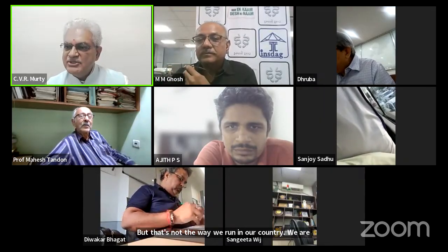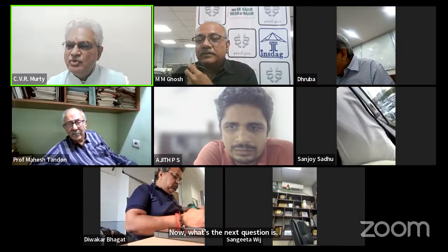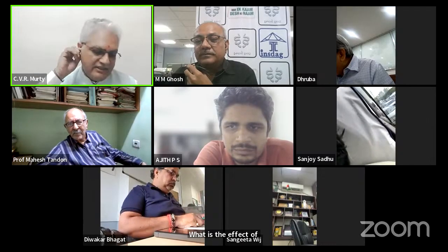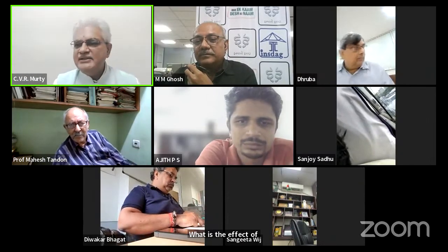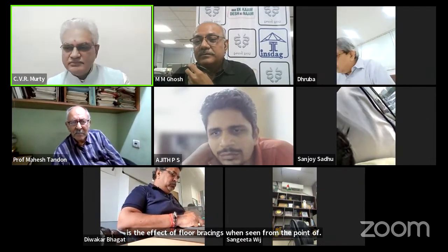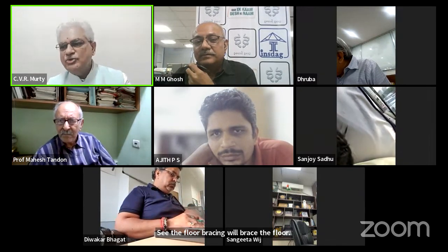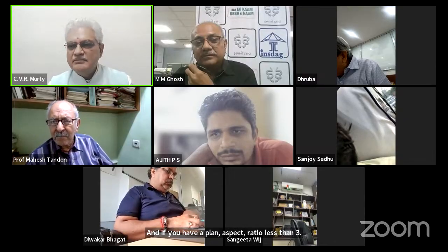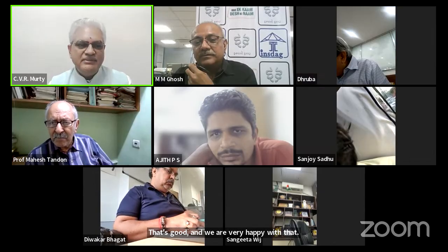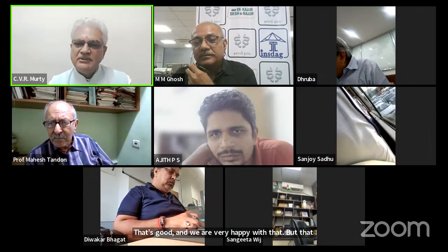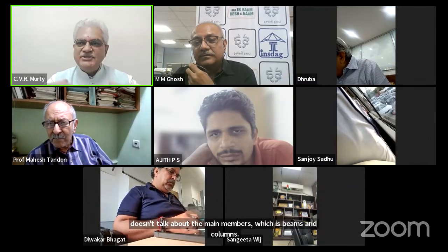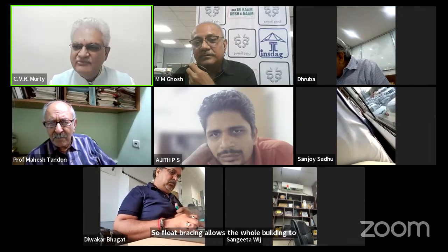Now, what's the next question? What is the effect of floor bracings when seen from a ductility point of view? See, the floor bracing will brace the floor. And if you have a plan aspect ratio less than 3, that's good, and we are very happy with that. But that doesn't talk about the main members, which are beams and columns. So floor bracing allows the whole building to act like a box back and forth.